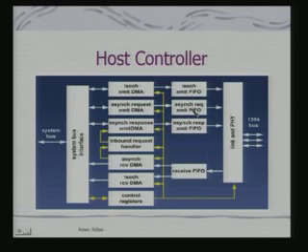These are all buffers, so therefore they have to be organized as FIFO, first in first out kind of structure. So this is an isochronous transmit FIFO, this is an asynchronous transmit FIFO, and this is an asynchronous response transmit.